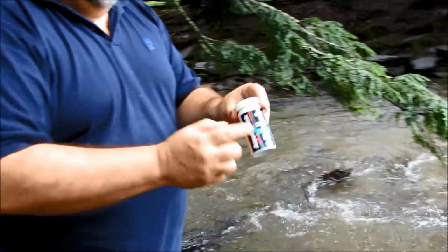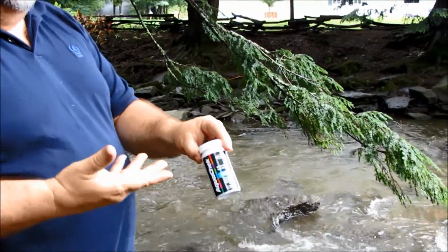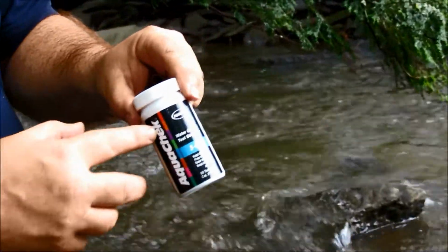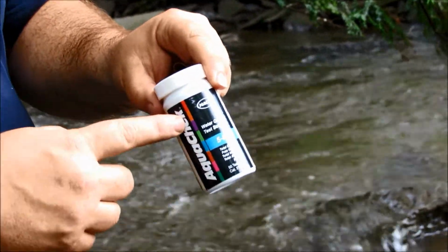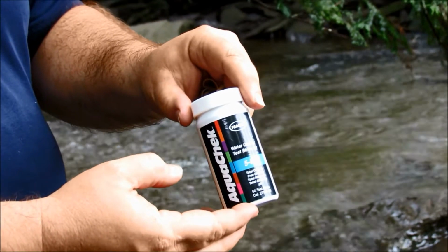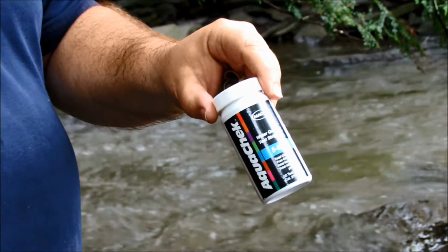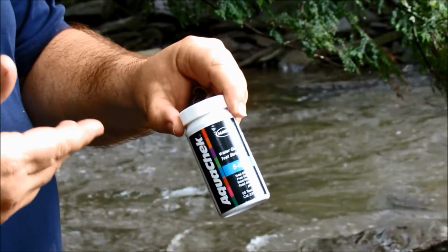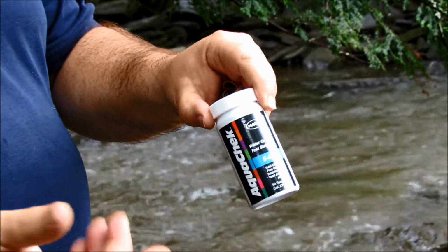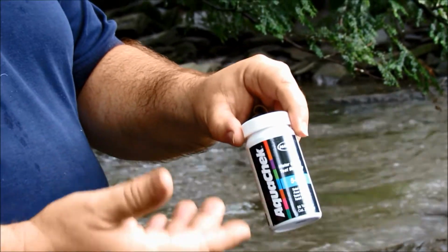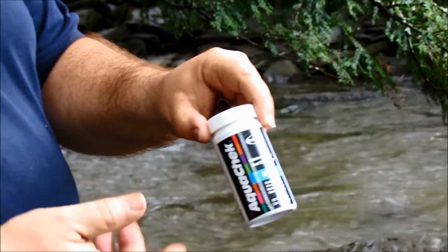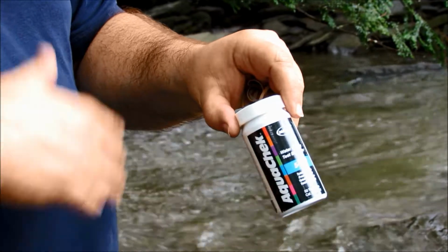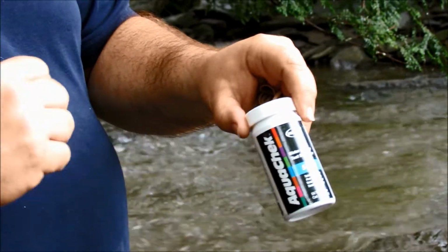Hach Company sells another product that I like. It's a 5-in-1 test kit. You can do chlorine residual, alkalinity, hardness, and pH. We use this a lot, especially when homeowners have shock disinfected the well. We want to make sure it was purged enough before they take a bacterial sample. So for homeowners doing shock well disinfections because they have bacteria, I'll say purge the well, check the chlorine level, make sure it's not detectable, and then we'll run that sample.